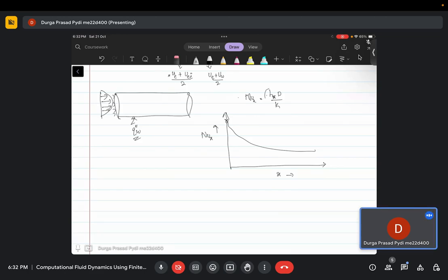You know all these things. The only thing that is unknown to you is this heat transfer coefficient, Hx. So how do you define your Hx? You have your wall flux, which can be written as h times wall temperature minus some reference temperature. You have to fix some reference temperature to get your value of H. Your wall temperature is again a function of x, right?